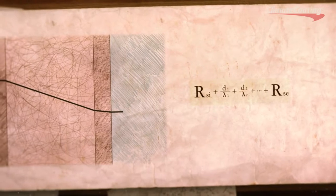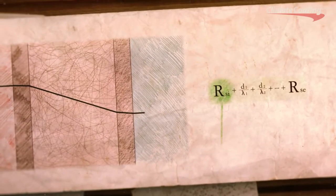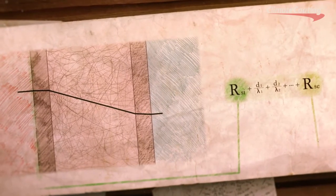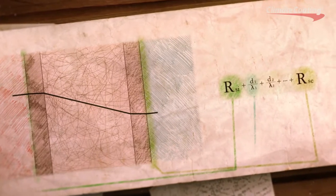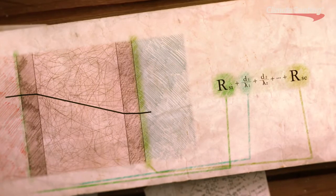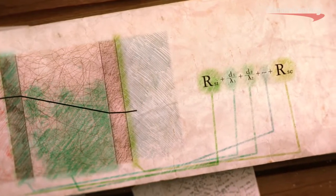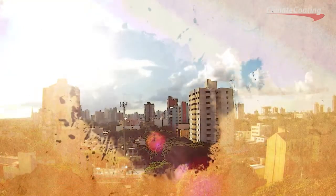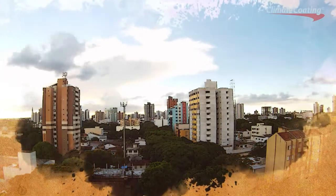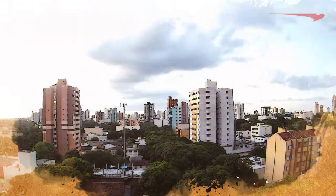This heat transfer coefficient of the wall is built up by the resistance of both inside and outside. Of course, they are DIN standardized and are treated as steady. The wall consists of independent layers of construction material which are specified by their thickness and value of heat conduction. For most buildings without insulation, U-values of 1.2 are known.